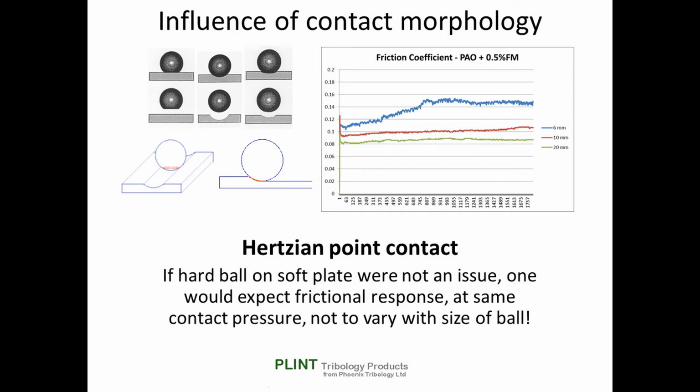Exactly this effect is evident in many reciprocating ball on flat tests, with ball wear scars showing an elliptical wear scar with grooving in the direction of motion, plus end of stroke witness marks which lack directionality.